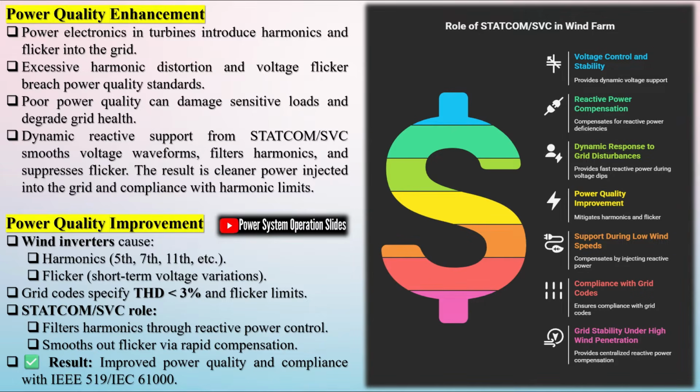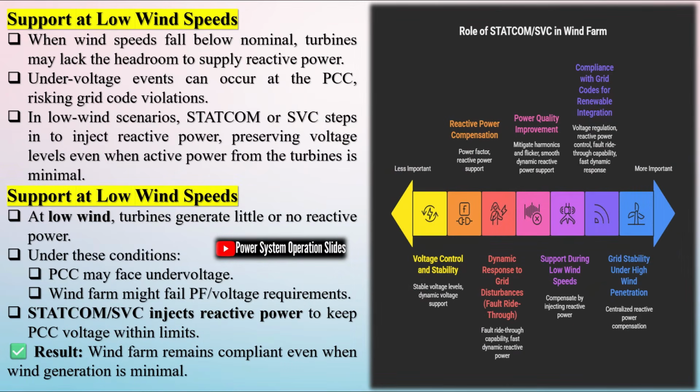The working principle of a static synchronous compensator, Statcom, revolves around its ability to inject or absorb reactive power into an electrical grid to maintain voltage stability. This is achieved by generating a controllable AC voltage that is synchronized in frequency with the grid voltage, using advanced power electronic converters. The core of this system is the voltage source converter (VSC), which transforms a steady DC voltage provided by a DC capacitor into an AC waveform that matches the grid's frequency and phase. The VSC typically employs high-performance semiconductor devices such as insulated gate bipolar transistors (IGBTs) or gate turn-off thyristors (GTOs) to ensure precise and rapid switching.